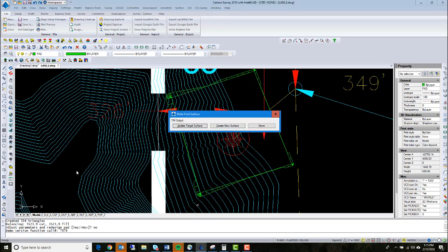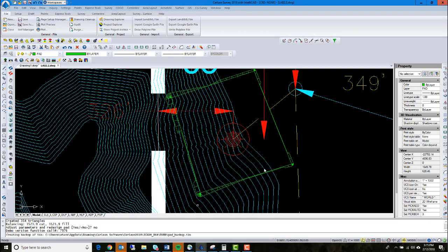And then you can see the contours are all sloping down here, so I'm cutting into the hill there, and I'm going to have to fill over here, so I can actually make the contours meet what they really look like. So I'll say yes, let's update those. Now it's going to take off and do quite a bit of work to try to now trim all those out and run. So just let it run for a while and it'll come back here shortly to you.